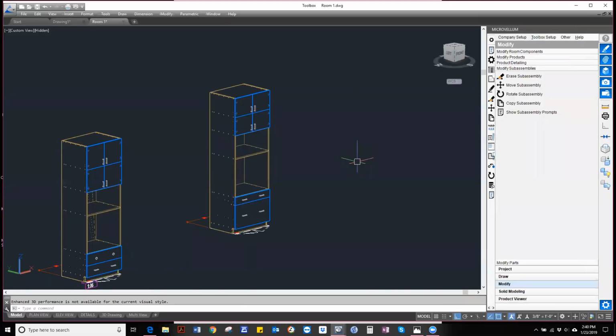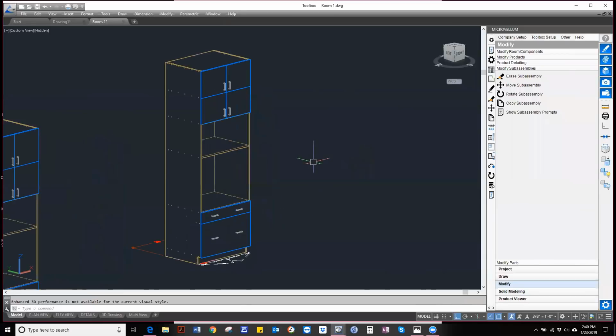If you hard code it and you change that drawer inside of this one subassembly, and then the client changes them all to 9-inch pulls, it's not going to modify that because you've already trumped that formula inside of there to look back up the tree. So always kind of remember when you're changing that stuff, how is it going to be affected, and are you going to possibly have to change those things down the road? All right. So you can modify these any way that you need them to be.